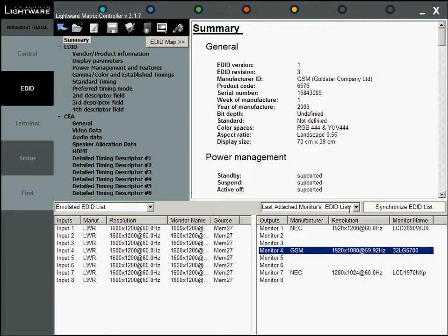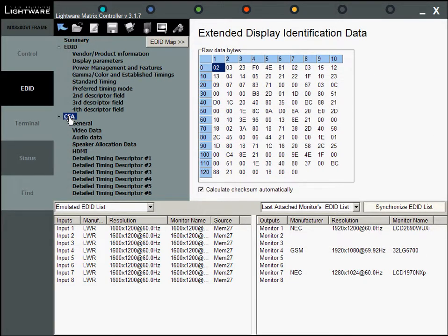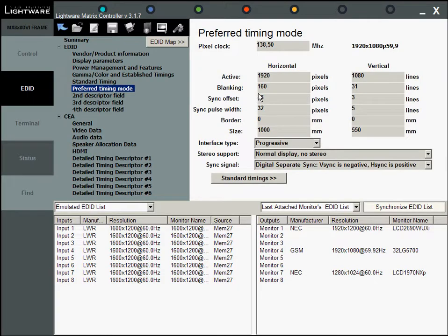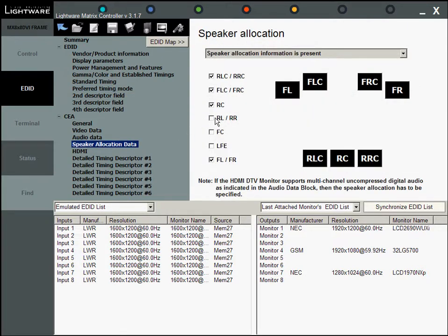The Advanced EDID Editor gives more sophisticated options for creating a new or editing an existing EDID. It turns the hex numbers in the 128 or 256 bytes of EDID, which are loved only by mathematicians and obsessive experts, into meaningful parameters with the possibility of adjusting or just checking them. The software helps to set even the much nuanced details that the EDID structure allows, ensuring the creation of the most suitable EDID that the application needs.